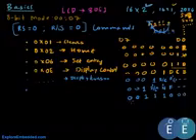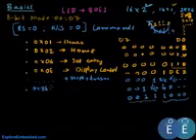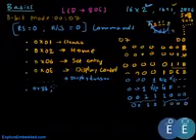So this would be 0x38 for the 8-bit mode, and we'll also be doing 4-bit mode. For the 4-bit mode, this would be 0, and this would be 1 again, so this would be 0x28. This would be for 4-bit mode. Okay, so let me just clear this up.